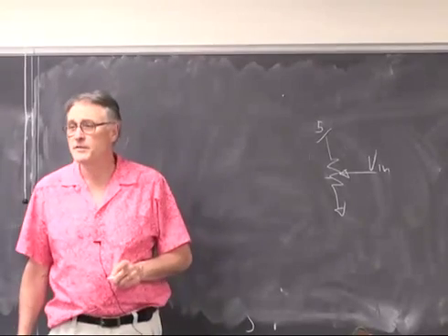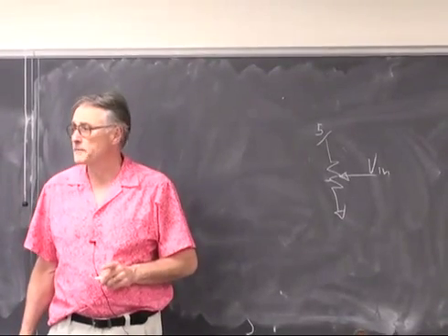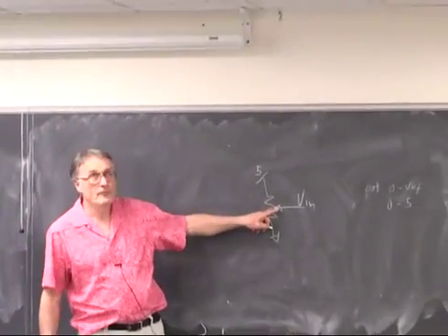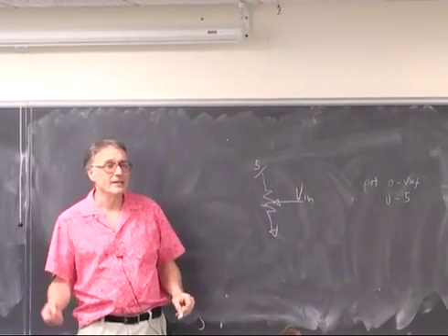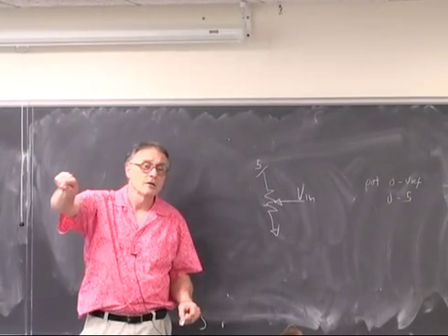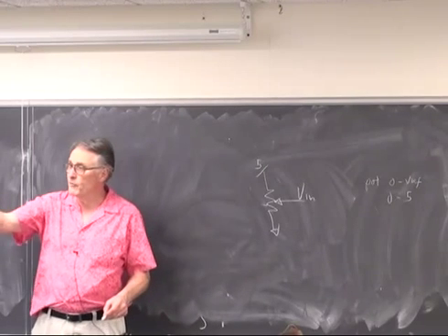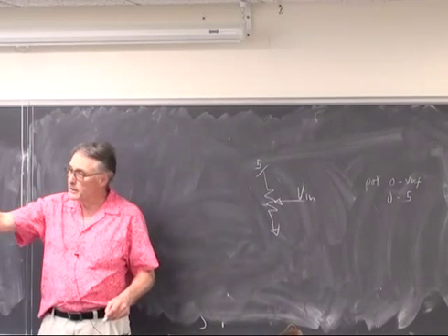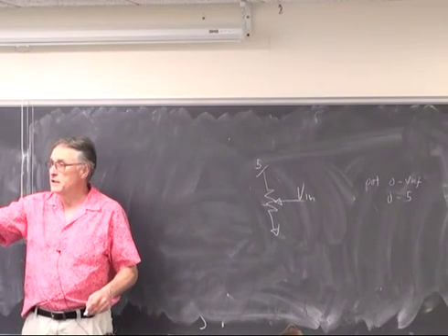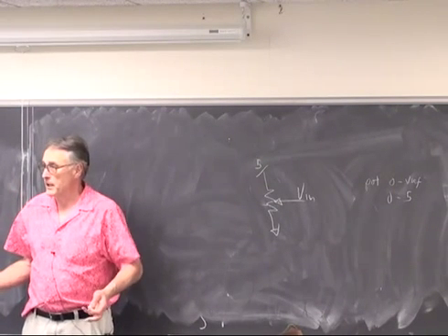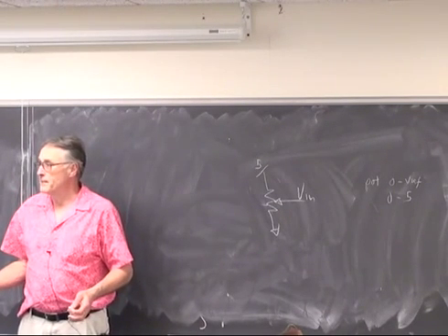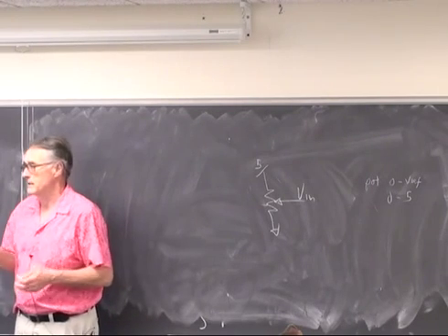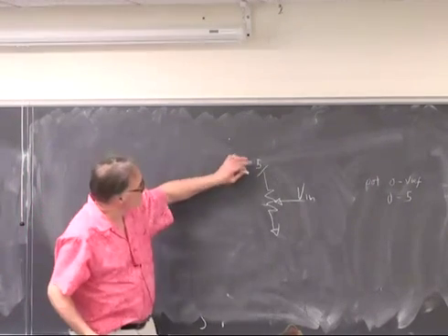But what if VREF is 1.1 volts? Then 8/10 of this trim pot is out of range, because once you get above 1.1 volt on the trim pot, the A to D converter will just read saturated, full scale.